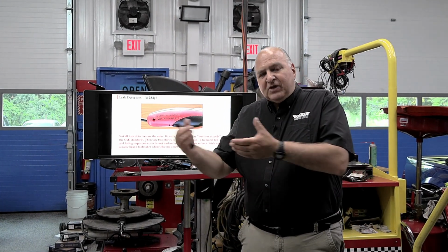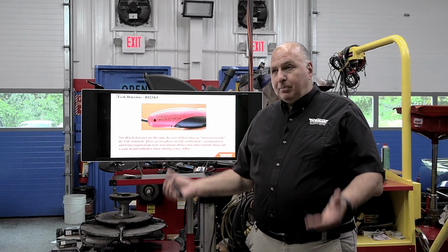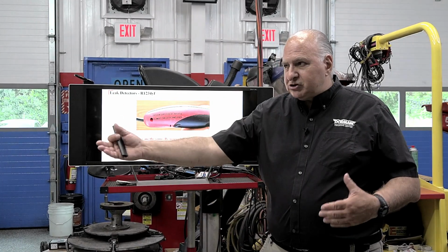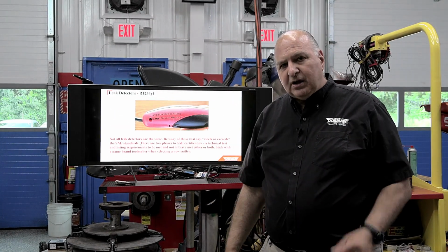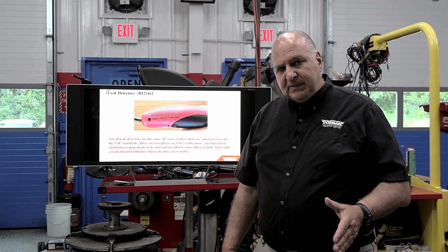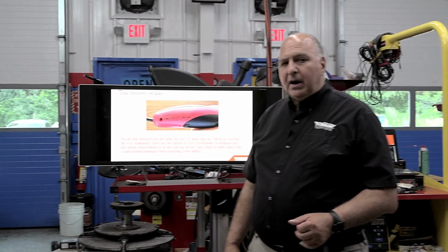So if you only put 15% in and beep, beep, beep, it's leaking, you pull it back out right away. And it does ask you the questions, whether it's Snap-on, CPS, or any other brand. It's going to ask you, did you perform that test? Did it pass or did it fail? And you want to cover your butt.